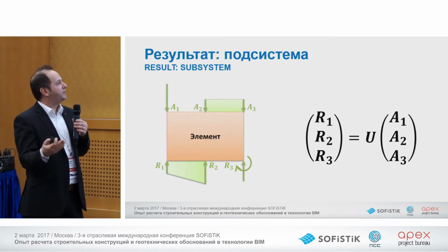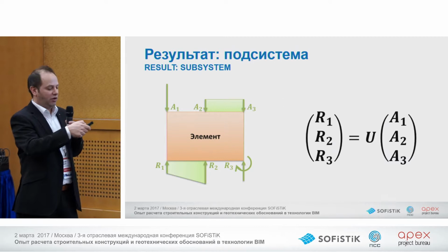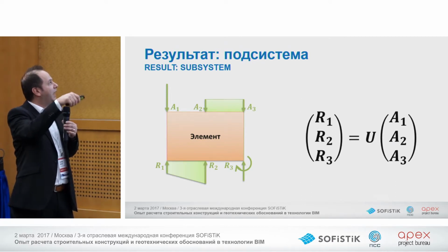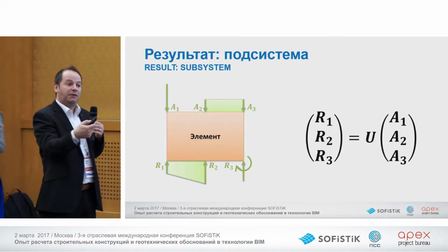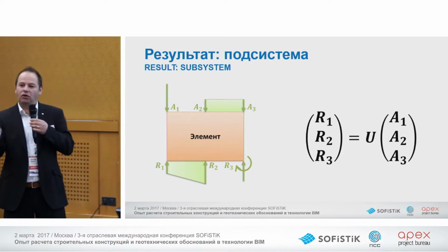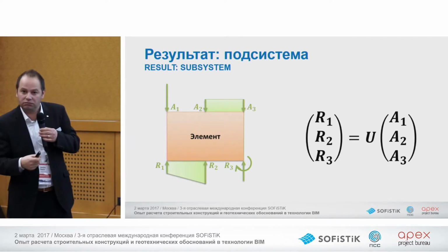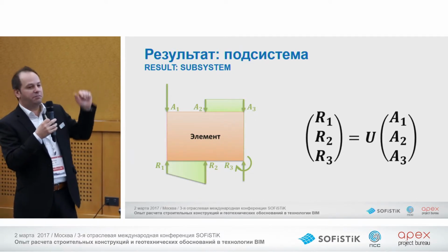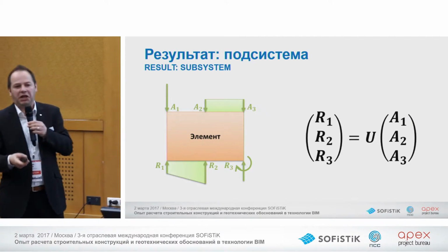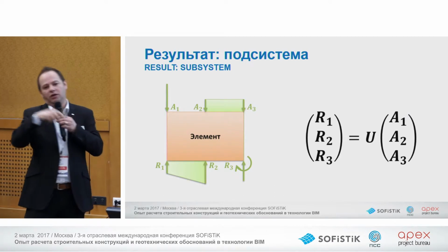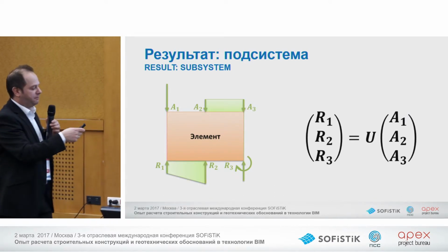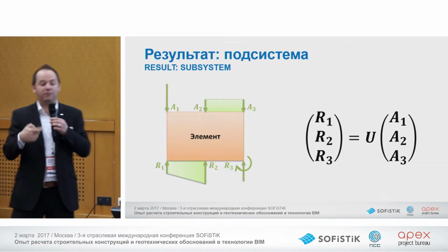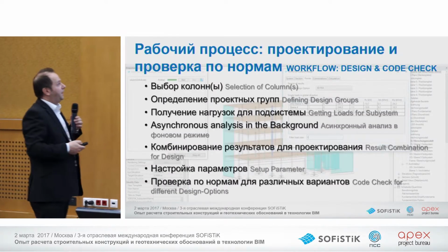So first thing maybe is that we can do a finite element analysis of this shell. So we can support these elements, we can create a mesh, we can apply loads, and then we can run a finite element analysis to understand how many loads go to the left support and how many loads go to the right support. The other possibility, maybe it's quite a simple one. We can have, maybe if this is a beam with 2 points as a support at the left and the right, we can take the left, the half of the loads goes to the left and the other half goes to the right. So we have many possibilities here also to drive this connection between all our members, and that's quite important. Okay, so that means,